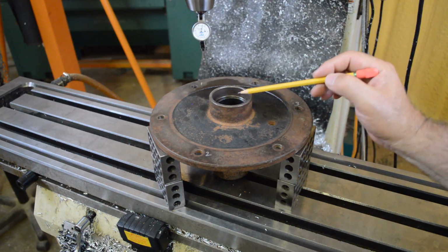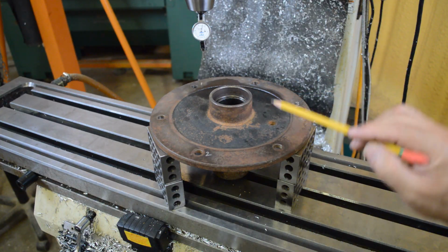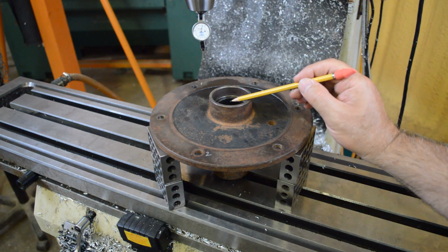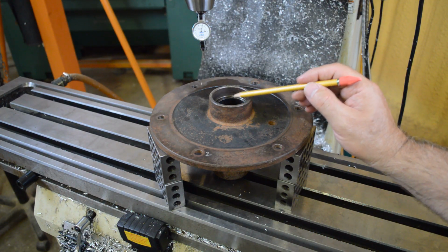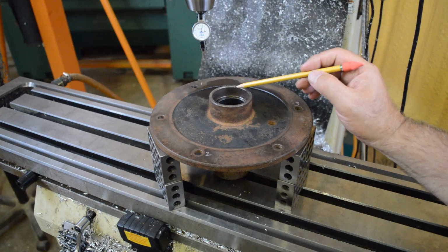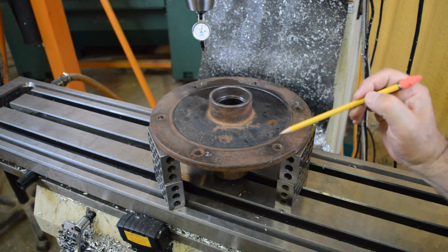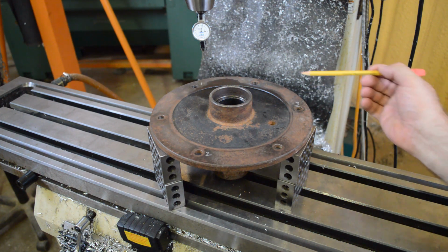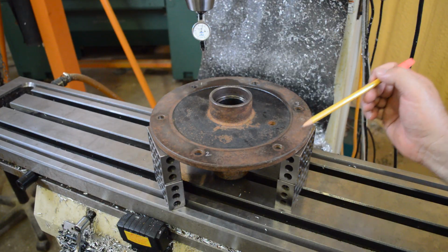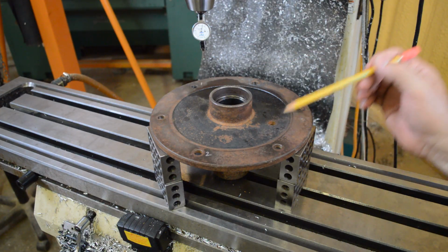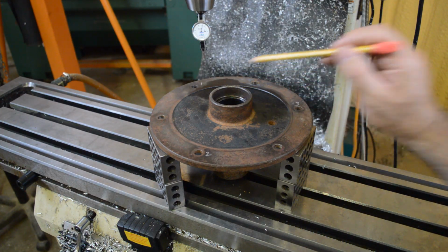that needs to be repaired. Just make believe that maybe this has been welded up because it was a spun bearing or something. So we need to be able to find the center line of where this new bore is going to go. Well, it might be a safe thing to conclude that this feature in the middle is on the same center line as this bolt hole circle, okay? So in that case, all we really need to do is pick up any 3 of these holes and define a circle through 3 points, and the center of that circle is going to be where we need to do our machining to do this repair, okay?